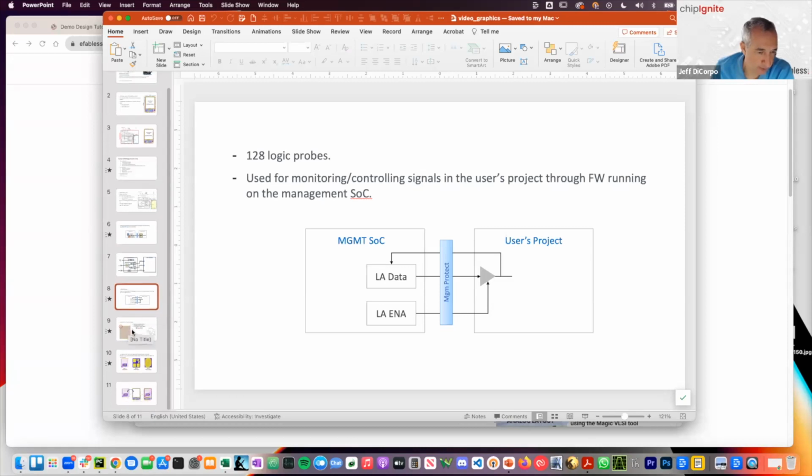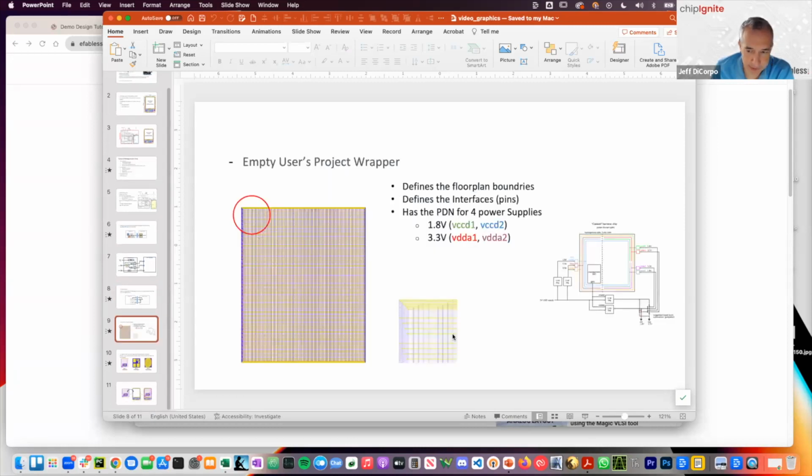And I think it was power domains, right? So the other comment is there are up to 4 power domains, 2 digital and 2 analog. For simple designs, you're primarily connecting to the single digital power domain for OpenLane. That's what OpenLane will connect to and utilize by default, but you can connect to these other domains as well if you have a need based on your design requirements.